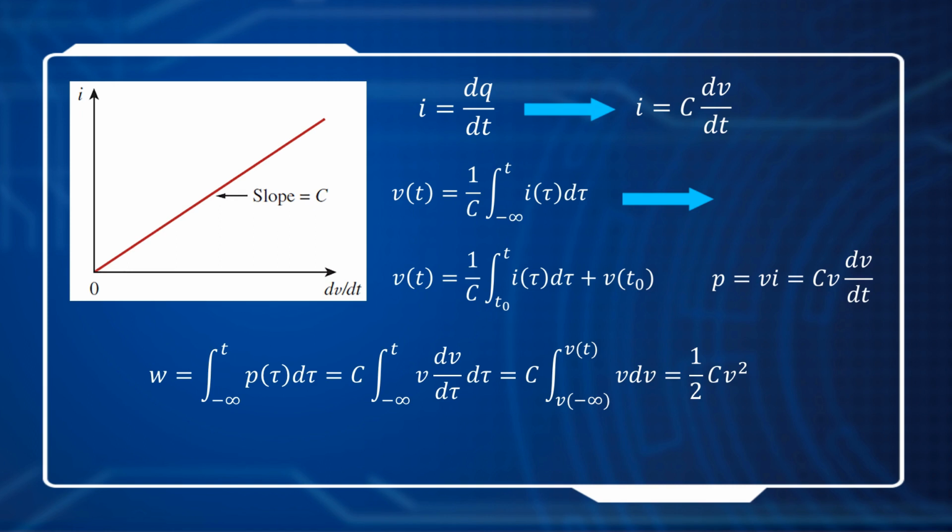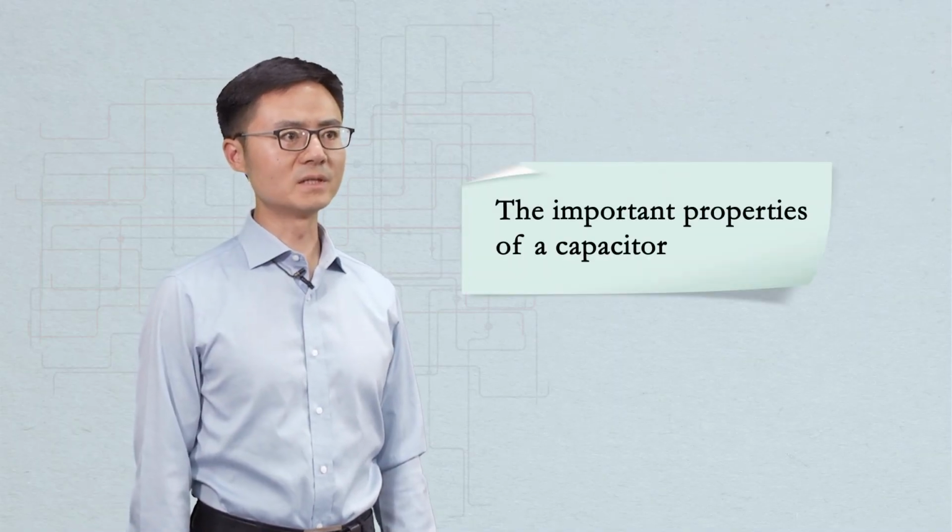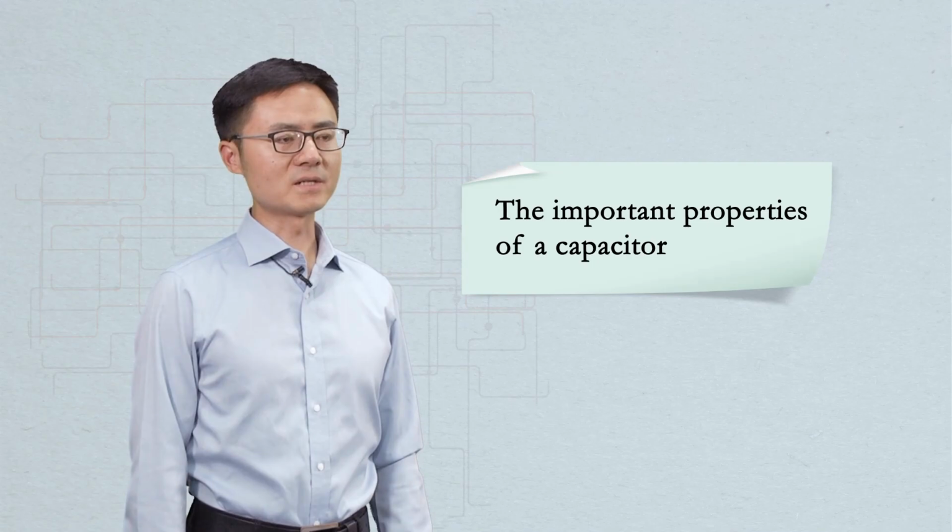Finally, we get the equation of the energy stored in the capacitor: W equals 1 over 2 multiplied by C multiplied by V squared. We can also calculate the energy with the charge stored in the capacitor, which is W equals Q squared over 2 times C.